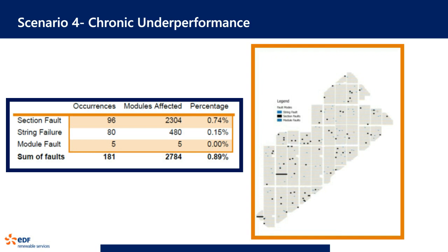say you're using 300-watt modules, right? They can be sold in 300s, 305s, 310s, 315s. None of those modules are ever exactly 300 watts. Every batch is really between, just to keep it simple, 300 and 304.9 watts. So if you have a 5-watt difference over a 300-watt panel, you're looking at about 3/4 to just under 1% of performance difference across modules within a group. All of this means that your model is only ever going to be an approximation of what happens.